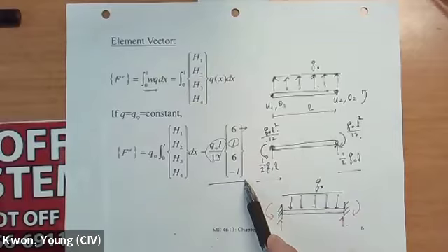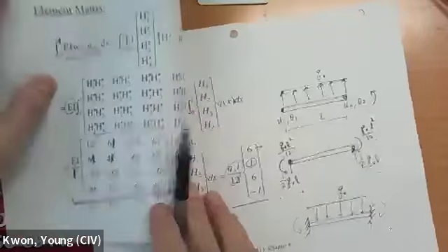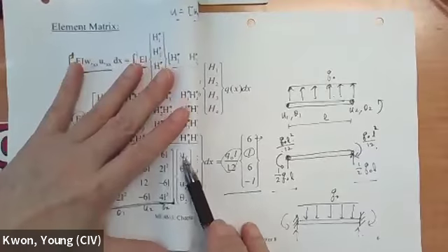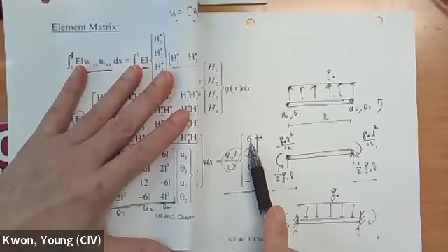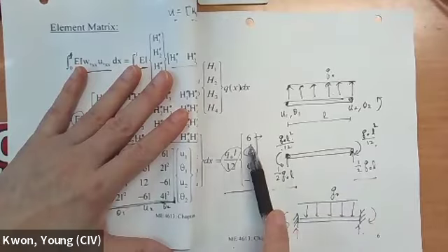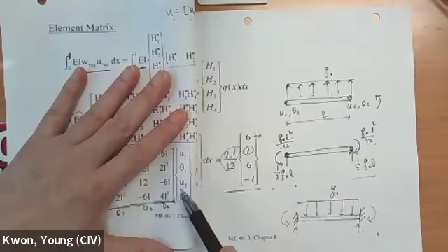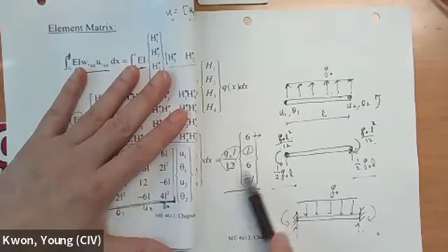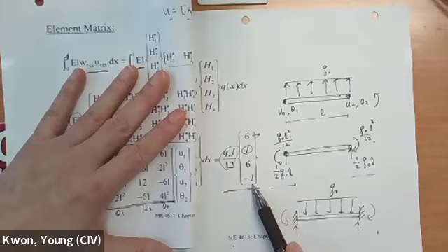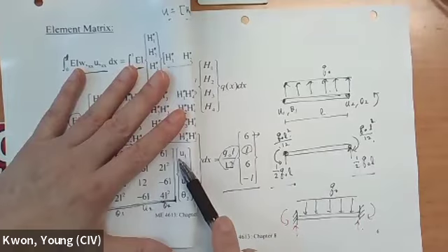Okay, in other words, if you look at this, displacement on the left-hand side, then on the right-hand side this column vector indicates the force. Displacement, force; this is going to be slope, that's going to be moment. Displacement, force, slope, moment. Why do they have to be like that? Because force times displacement is what?